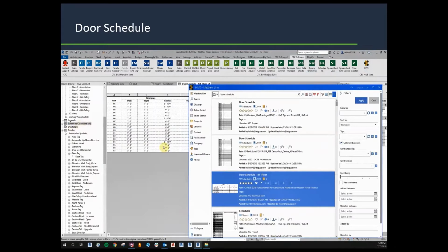And one of the cool things about Revit is that this is a quantity reporting schedule, and it's not pre-filled out, but you can see that it has filled itself out. When I load that schedule in, it brings over all of the formatting and the columns I want reported, but it uses my project to fill in the data automatically. So I just drag the schedule in and boom, it has filled itself out.